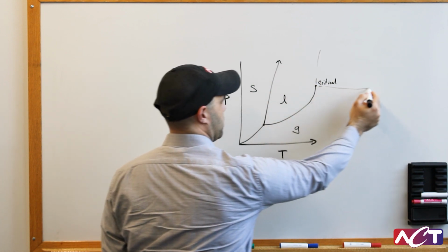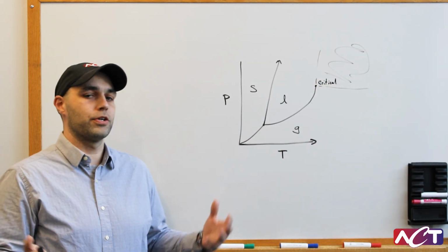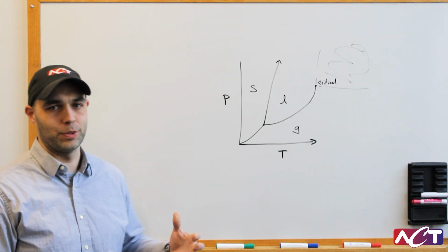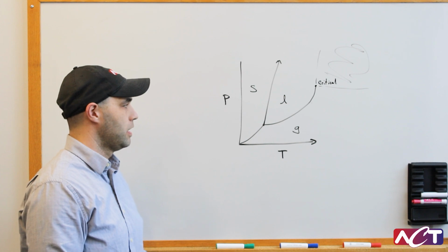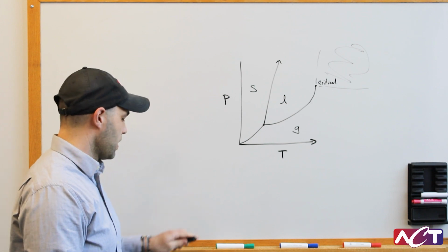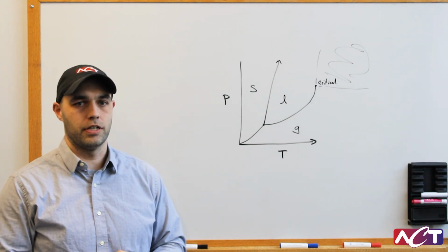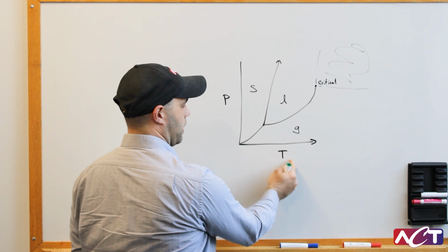Beyond this, in this region, is what's called supercritical fluids. Strange things happen up there. We don't have normal phase change, so they don't work very appropriately for pump two-phase. So one of the first considerations is what temperature is your application working at? Is your fluid in that temperature?